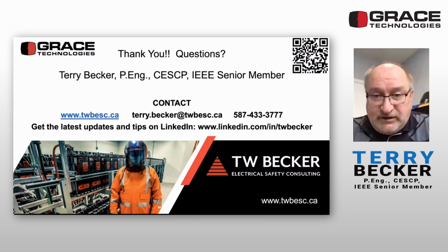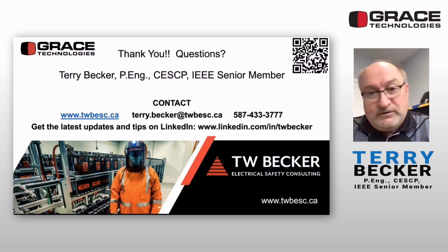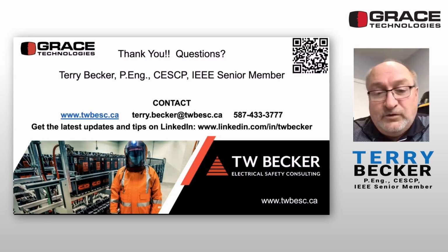So this is the electrical hazard classification and electrical hazard identification that, under your electrical safety program, take the work task table, which is now Table 2 in Z462. Create your own version of it, right? Add a shock column to it, and then keep that generically against what are we working on? What's the diagnostic or testing for absence going to be on? Well, it's going to be on 1500 volts DC. Whoa, 1500 volts DC, I can get a fatal shock and an abnormal arcing fault can be sustained.